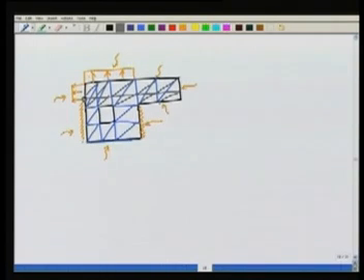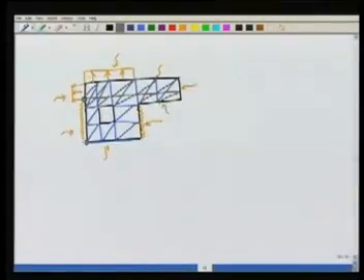There are times when, in fact this is always going to be the case in practical problems, that the boundary conditions decide how many boundary segments we are going to define a priori, and from there we have to first honor the existence of this transition of boundary conditions while putting nodes. So this has to be a node, this has to be a node, this has to be a node, this has to be a node. All these have to be nodes, because the boundary conditions are transitioning, as well as in certain points the geometry is transitioning. For example, here the boundary conditions are similar, but the geometry has a change. So I have to honor those. These nodes I have to put. So these are the minimum number of nodes that I have to put in the definition of our mesh. So the new mesh is no longer what I had drawn earlier, it is actually these entities.